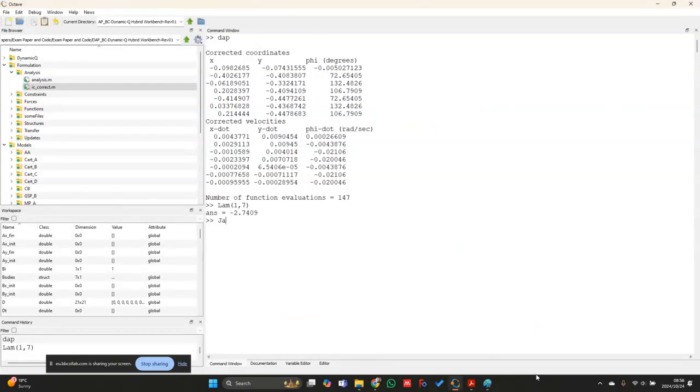Now its corresponding Jacobian sign will be 1, and I think it's 7, and this is then on body 1. So I'm considering the reaction forces on body 1 in this case. So that would then be 1, I think. And I can see in this case, I do indeed get this answer equal to 1. So that simply means that the reaction force caused by the revolute joint between bodies A1 and A2, or point A on body 1 and body 2, is then minus 2.741 Newton, since I just multiplied by 1.